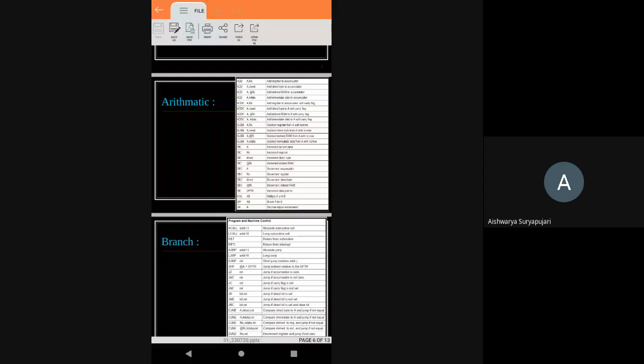Like this is the meaning of this one, that is add direct byte to the accumulator. Third one, that is add A, @Ri. Again this i stands for the 0, 1, 2, 3 values. So here you can read the description that add indirect RAM to the accumulator.